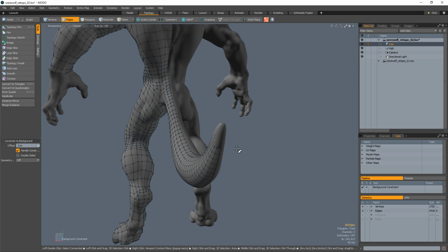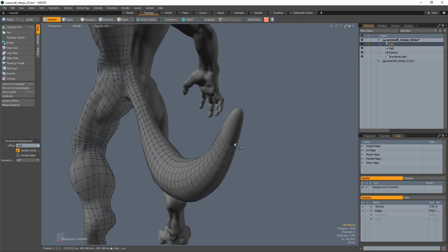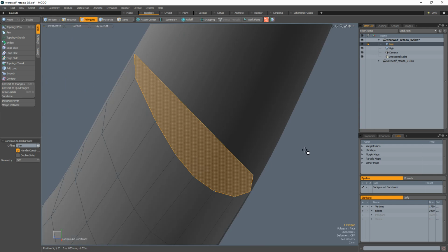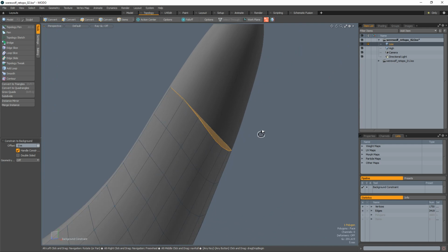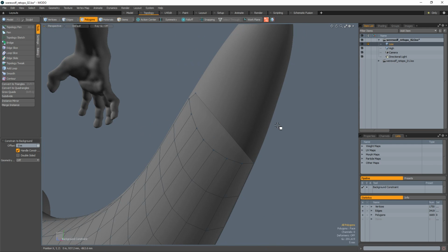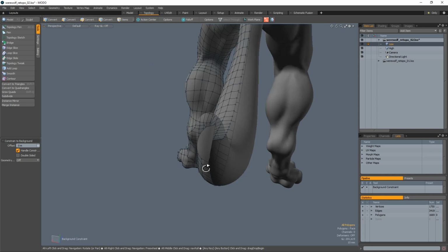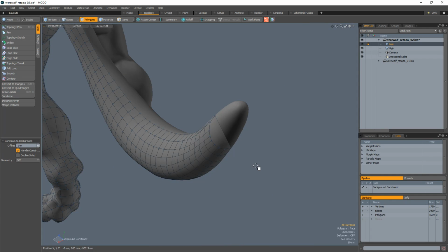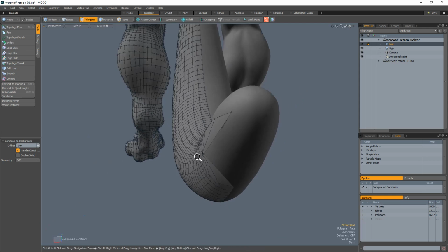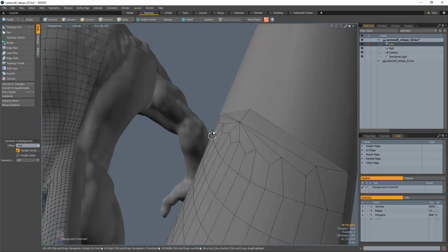and talk about some different ways that you can do it, and then I'll talk about the way that I prefer to do it and why. So there are a couple ways that you can do this. The first one is to obviously just take all these points, make a simple polygon out of them, and there you go. There's a little cap on his tail. It's done-ish. You will run into problems if you want to subdivide this, though, because you start getting bizarre shapes like this.